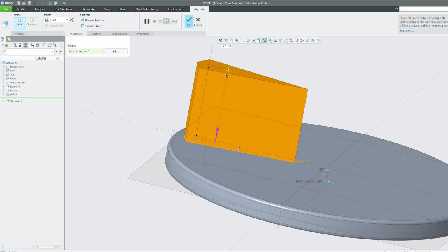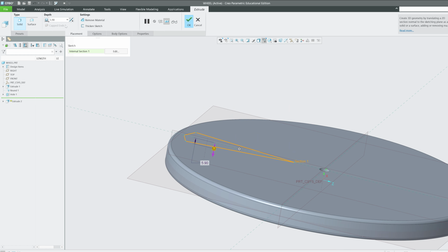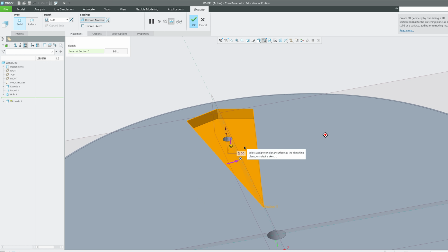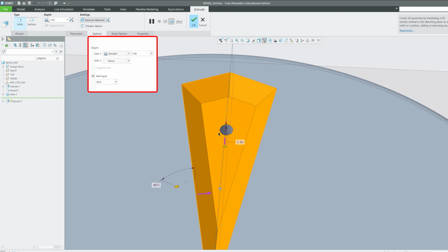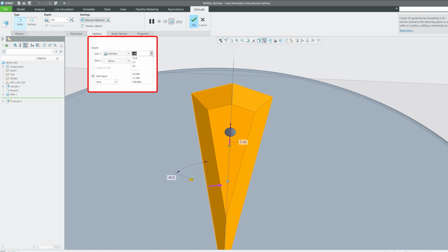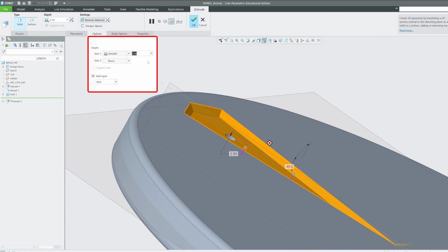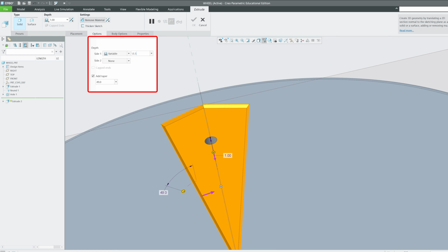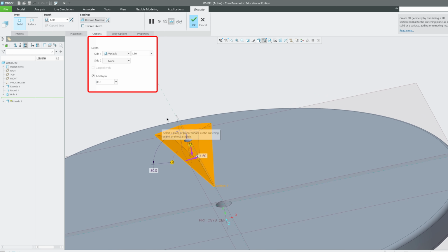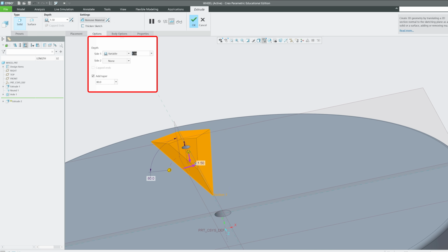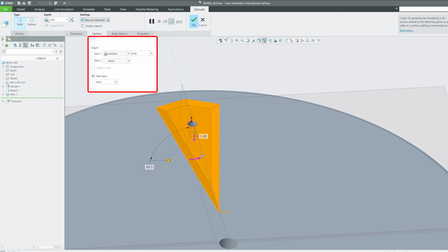Now comes the interesting part. So of course I'm gonna remove the material, but now to make it look more 3D, we can add a little bit of taper here. So I can click on add taper, and now I'm gonna add this kind of taper, and let's reduce the depth actually. So I'm gonna make it like shallow depth, yeah, to 1.5 probably, and let's add more angle actually here, 80 degree. Yeah, 80 degree looks good, but we can reduce the taper then. 0.8. How about 0.8? Yeah, this looks good.